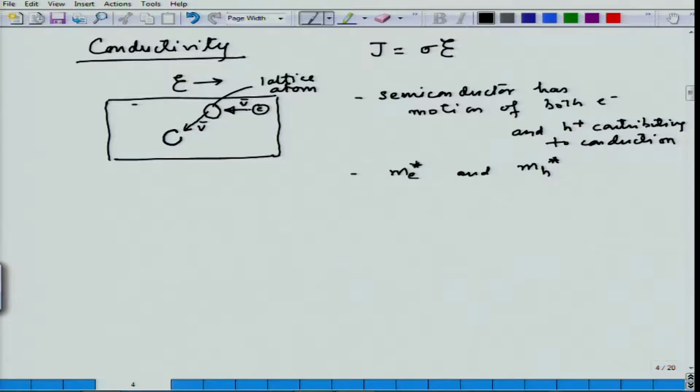It may again have a collision with impurities in the material, acceptors and donors, which could be dopants or deep level impurities, mainly dopants, because the dopant concentration is much higher than the impurity concentration, so that is a major effect.